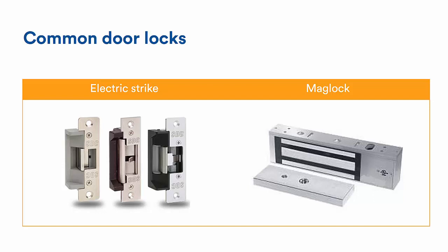Fail-safe electric strikes can't be used for stairwell re-entry because fire doors require fail-secure electric strikes for positive latching. Fire doors do not require fail-secure electric locks, only fail-secure electric strikes. Electric strikes are a common and favored option for interior, office, or single-door passageway openings.